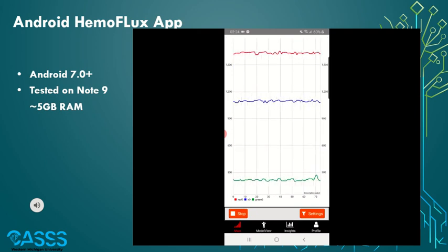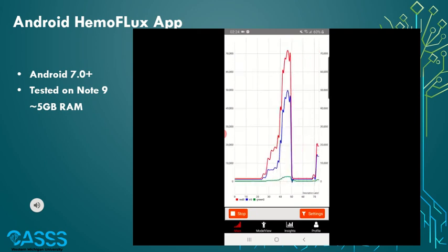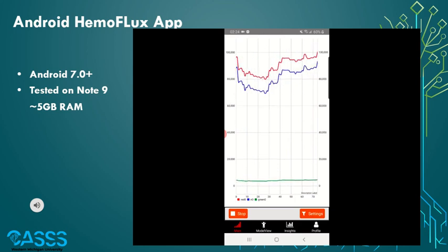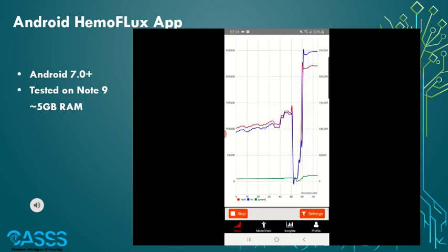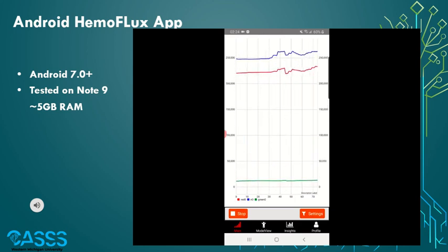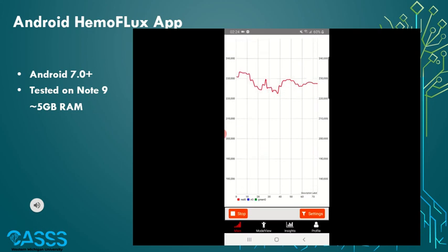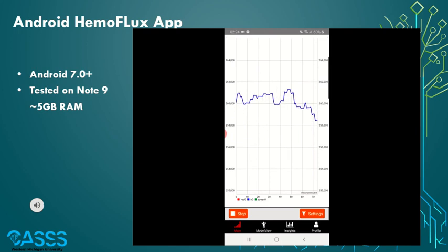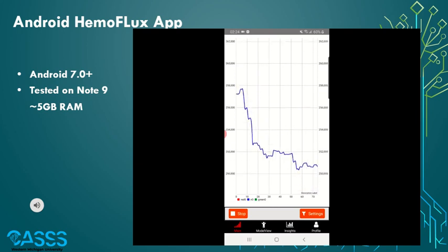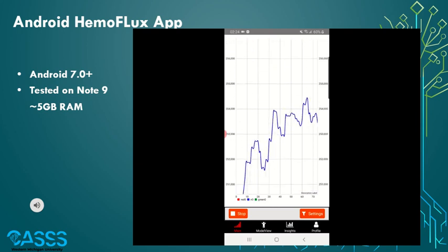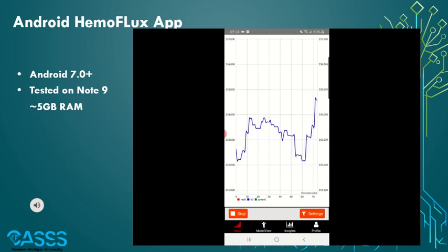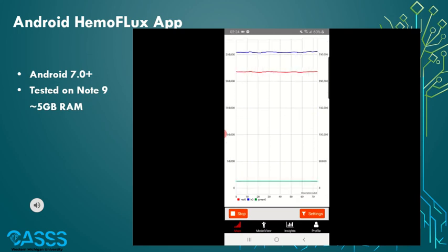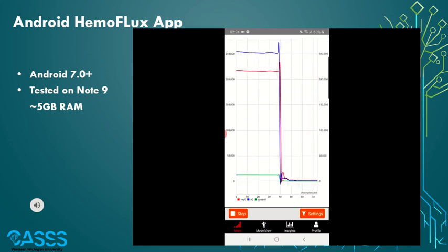And this is configured right now with one PPG. And as you can see the red, the IR, and the green values, you can see they differ by quite a lot, which was earlier demonstrated with our analysis of the AC and DC components of the PPG waveform. So I'm zooming in a little bit to show the actual variations as time moves along of the PPG waveform for the IR wavelength.